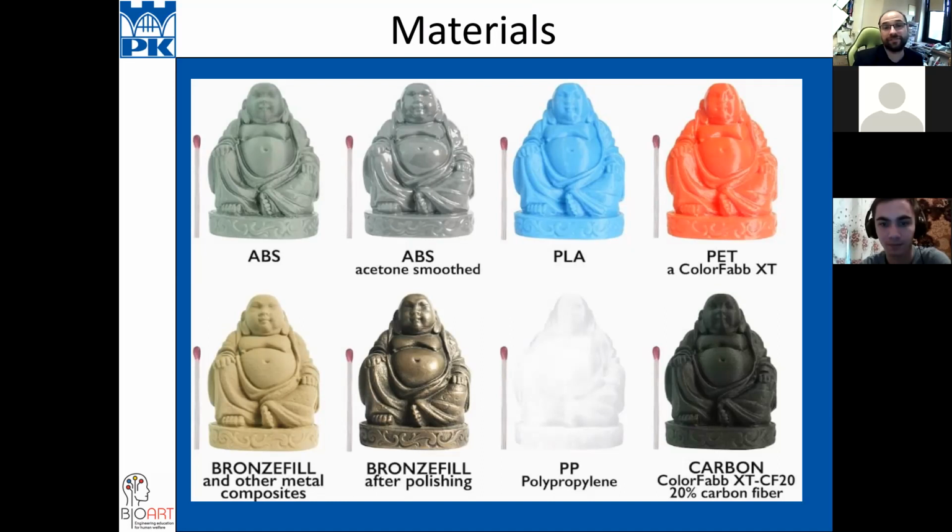Of course, the filament is very expensive because I know the Polish prices. It costs more or less 1,000 zlotys per kilogram. Of course, you need to use a special nozzle, but I printed with a regular bronze nozzle. The quality was good, but you know, when you have a lot of metal powder inside the filament, the nozzle will be destroyed very fast.